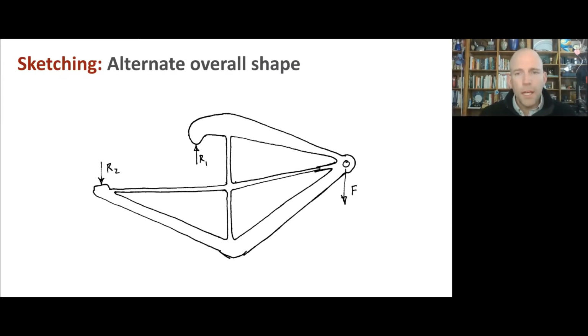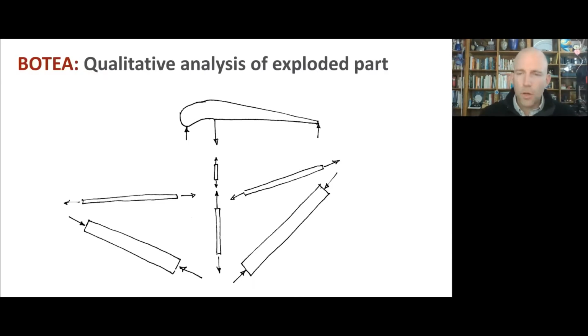So here we have, and let me blow it up for you because this qualitative free body diagram really helps to understand why things are like this, what they're intended to do. So to solve that problem of maintaining contact with the top of the table, we've got this element in 3-point bending, big force down, pretty big force up, just to the left of it, and a smaller force over here, far offset up. We've got a tapered cross section because we expect this is, if I cut here, this thing is kind of like a cantilever, and the bending moment is getting smaller and smaller as you get towards the tip.